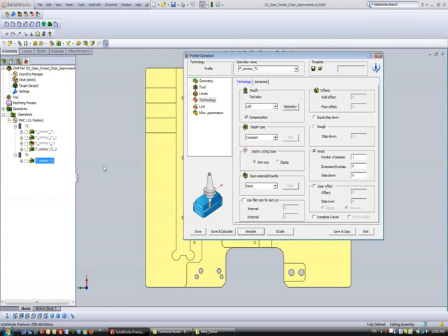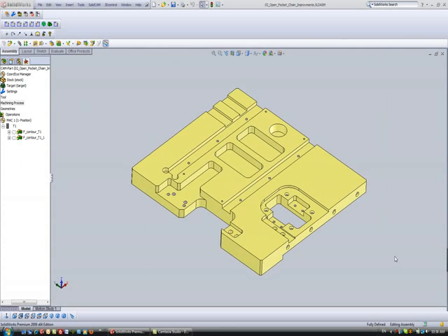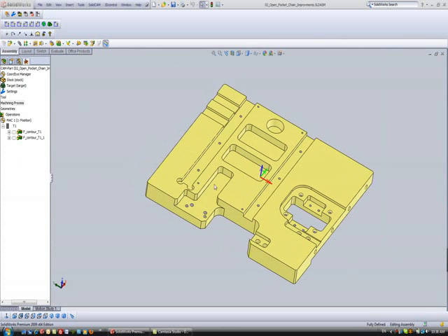So within one geometry, I was able to do two separate operations, using part of the chains in one geometry and all of the chains in the other operation. Now, one other thing I'd like to show here is how we work on this open pocket over here. You'll note that when we create a geometry, we'll have to create a geometry around this area, but mark this area as an open pocket.